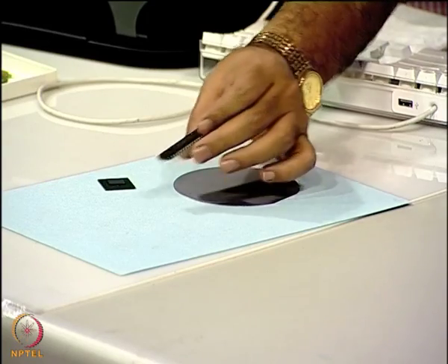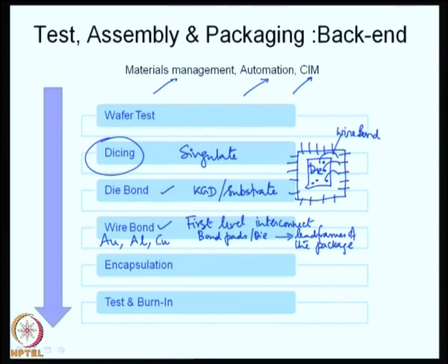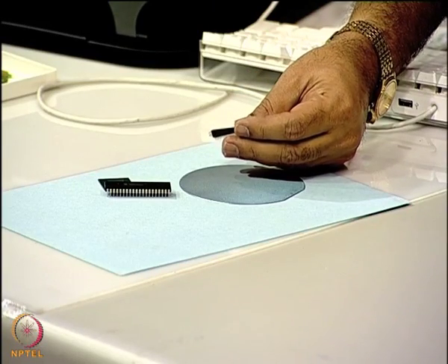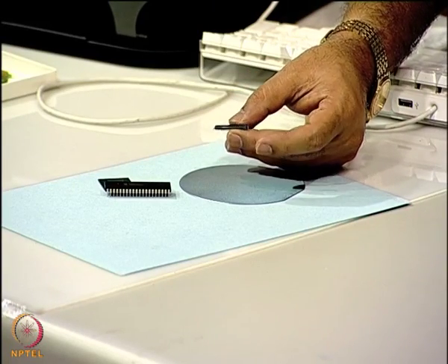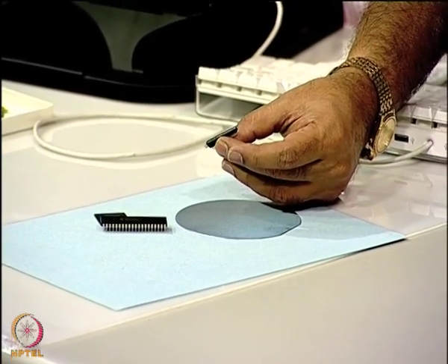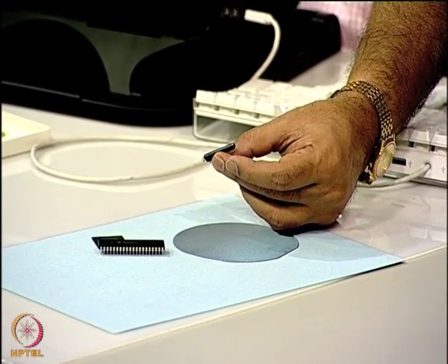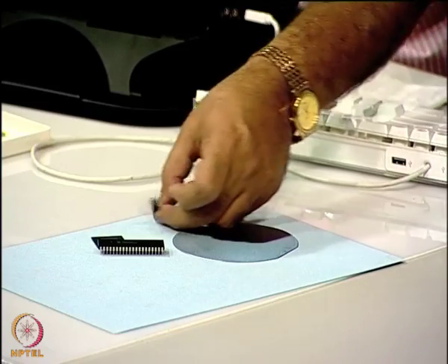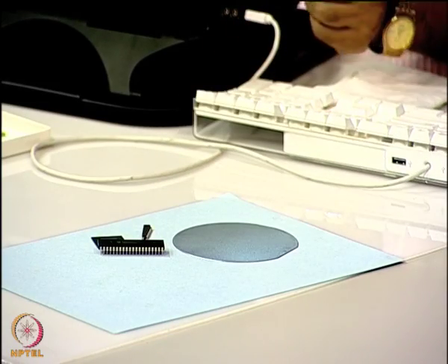That is how the first level interconnections are done. So, if I have opened up, I have cut a chip here, and if you can closely look at this chip, you will see the die and the wire bond interconnect going to the lead frame. So, this is a very important activity in the back end process of the semiconductor manufacturing.